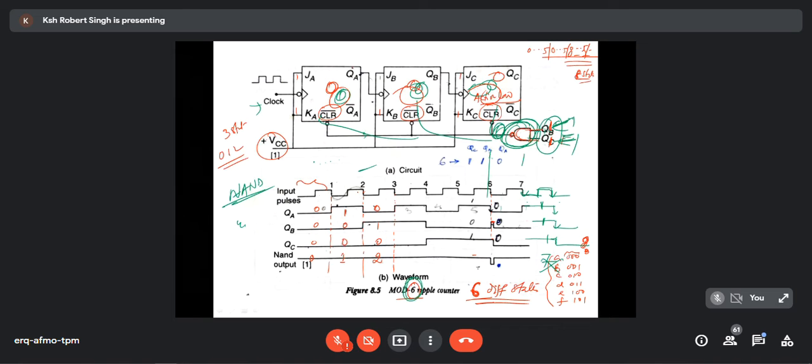Now, after this 2, you just see, this is a normal flow. Normally it should go like this. But I want intentionally this. After 2, I want this to be 0. That means I want to force this particular thing down to 0. This is already 0. Then what should be the input to this particular NAND gate? QA, QB. Exactly, QA, QB. Good. Because these 2 are not obeying. These 2 are high. You feed them there. Finish. Now, same question again.